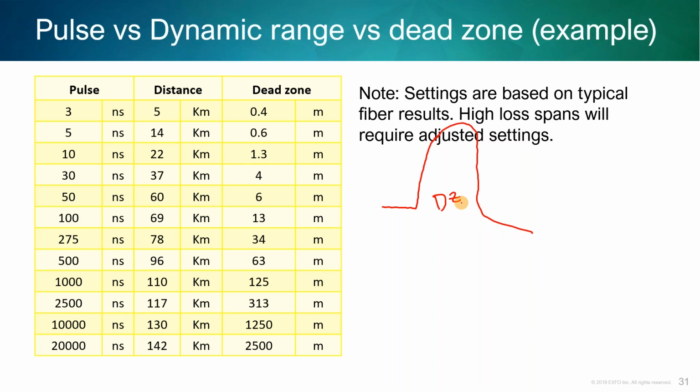It's like looking into high beams. You look into high beams and you adjust your eyes, you don't see 100 feet of the road. That's dead zone. You're still traveling across that pavement. You're just not knowing what you're hitting as you go across. So we know what the loss looks like going in. We know what the loss looks like coming out. We just don't know what's in here that caused the loss. Was it only one event? Was it only a connector? Or was it a connector and a pigtail splice? Or was it two connectors? Who knows? This is resolution.